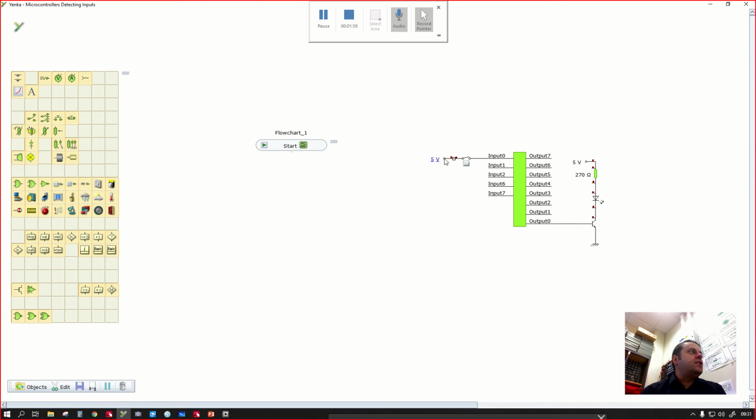You can see how you have to put a 5 volt supply going in. So essentially what we're doing is raising input 0 to 5 volts whenever we press this switch. This is good enough for National 5. This isn't actually how it's done in the real world. Highers learn that stuff later on. And I've wired a red LED to output 0.